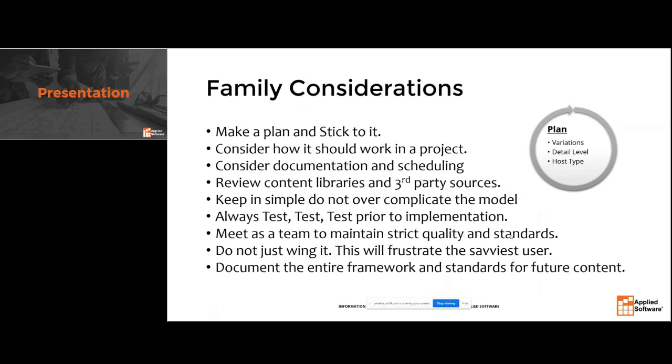You don't just create families off the cuff, because there's a lot of information and detail, not necessarily complexity in the family, but information and data, and performance really is the big one when you're generating families. It is possible to build a family that's too complicated and it just oversizes or bloats your project. You want to stay away from that.